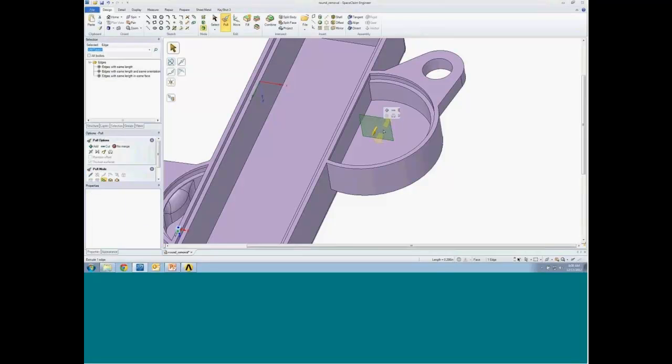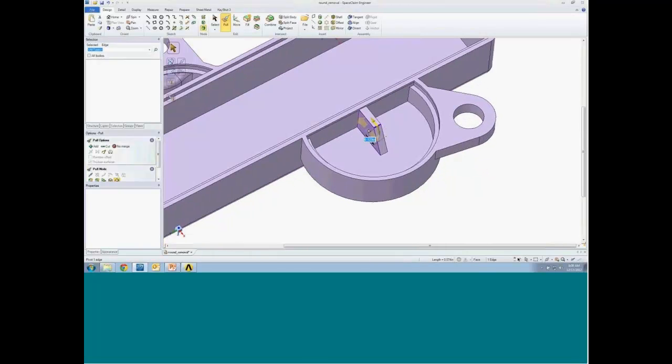I just have to start off with a line if I want to keep things very simple and pull that into a surface, and the surface extends into a solid body. And that actually is a section or a chunk, a member of the main body. And you see me using this pull tool. This is your primary creation, editing, deforming tool right here. If the pull tool creates, it's that fill tool that gets rid of. So I added a rib, nothing more than that.